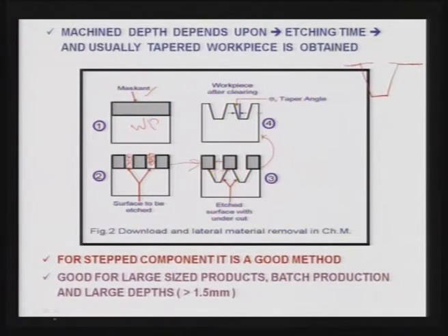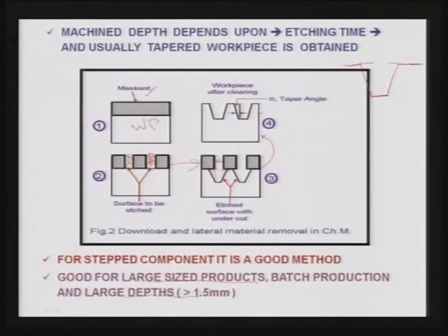For stepped components, it is a good method and good for large sized products, best for production in large depth. Now, for large size products, removal of the material like this is very comfortable compared to other methods where it consumes a lot of electrolyte or dielectric and a lot of time. Here it becomes much easier if you can mask it correctly. Also, very large depth cannot be done by this particular method.